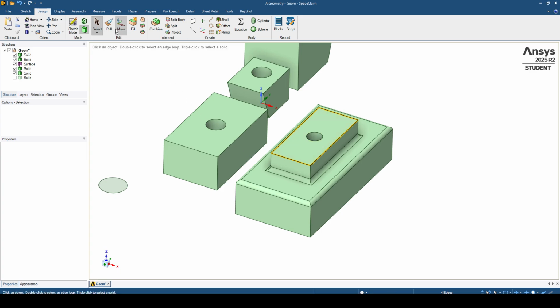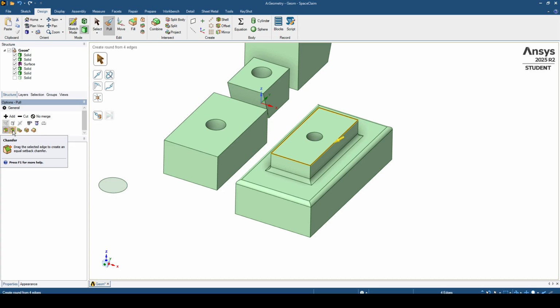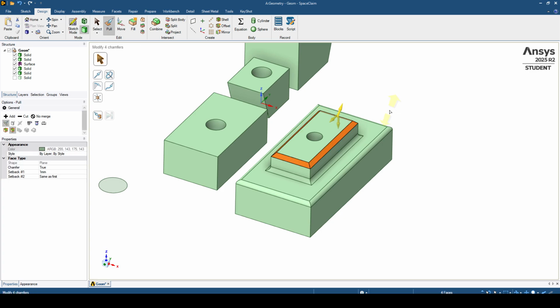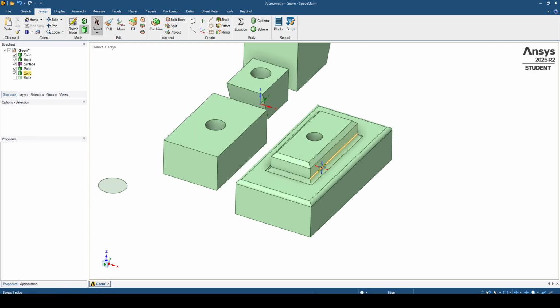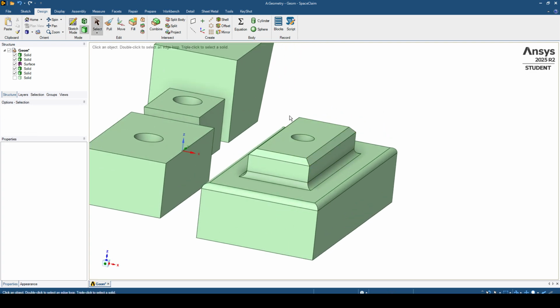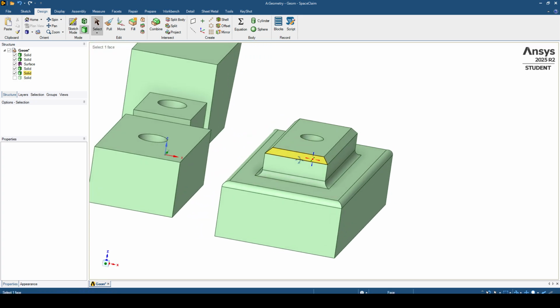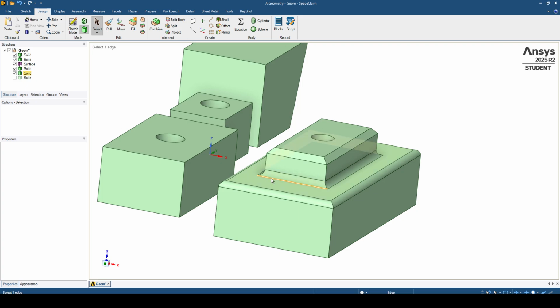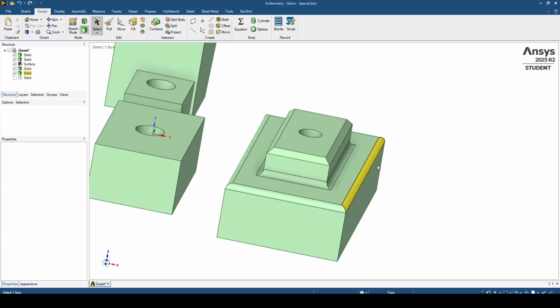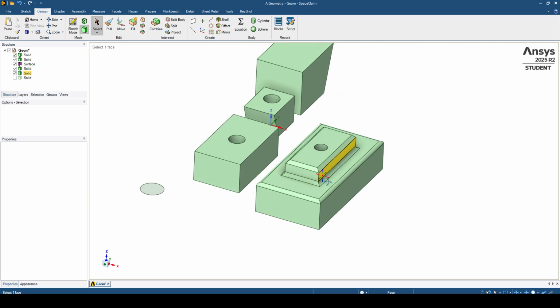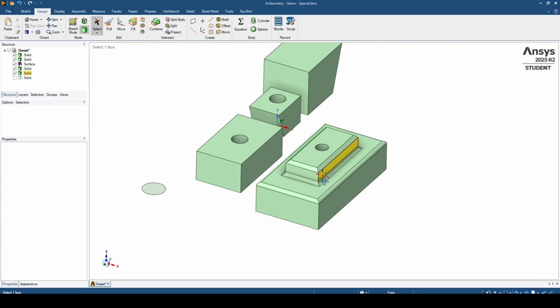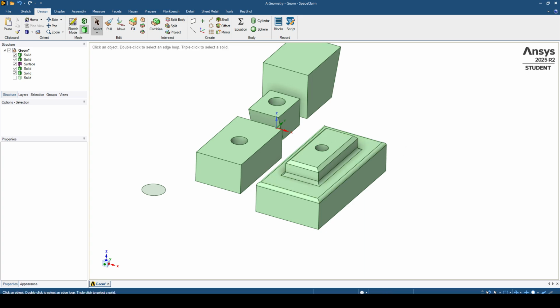I go to the Pull tool again, and instead of the first feature, which is the round here, we choose the second one, which is the chamfer feature. I will click on it and for example I will type 1 millimeter as you can see and hit enter. As you can see right now, instead of having fillet on the upper four edges here, we have chamfer, and on the down part here we have the fillet features. Now our part is way better than before and looks professional.